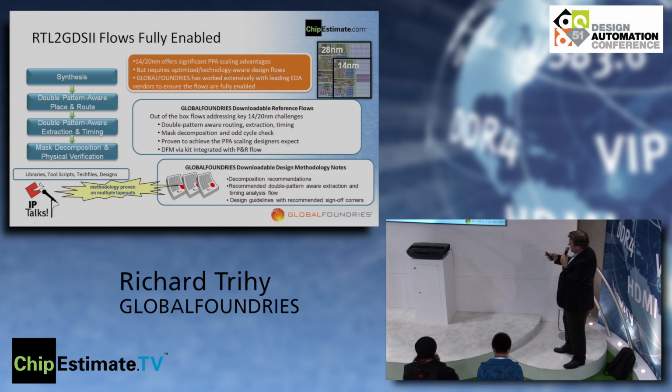So embedded in this are design guidelines, recommendations, how to do double patterning aware extraction. I talked earlier about the challenge with the variation. So we embed solutions here. We explain how we come up with those solutions and why you should use them. Okay. Also in these flows, we deliver design guidelines. And these design guidelines will provide margin recommendations, the temperature impact of the sign-off choices. Power mesh design. There's a whole host of guidelines provided along with these flows.